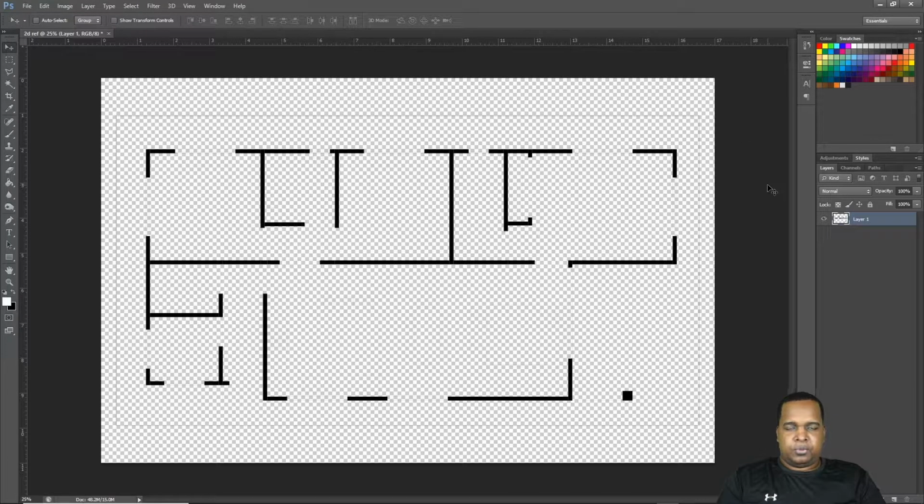So we open it. Now PDF doesn't have a background unless you create a background. It will be transparent. Since in AutoCAD we basically just draw the walls and everything within it, you would see this checkerboard at the back because there isn't a background. So what we do is we create a layer and we'll drag the layer to the bottom. We would rename this one a reference layer, and we'll just assign a color, so that way you would know this when you start to get mixed up with the files.